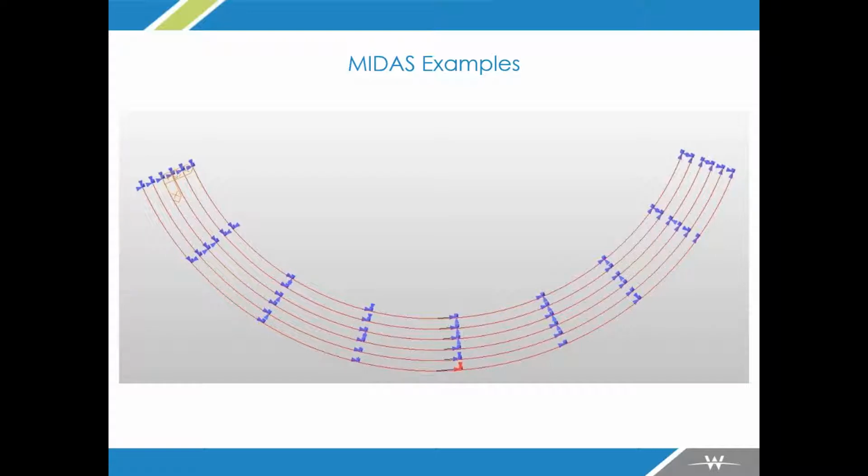Now, if you get into an existing structure that you're load rating that's already there, you really need to pay attention to what are the bearing settings. How restricted are those? Are they fully engaged to their maximum extent, and that they're actually going to provide more of a fixed or restrained condition in a certain direction, one or the other, transverse, longitudinal, however you're looking at it. That's really important when you get into analyzing the structure to make sure that those boundary conditions are correct.